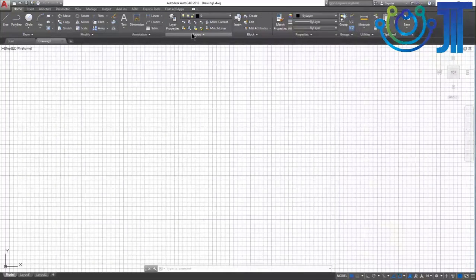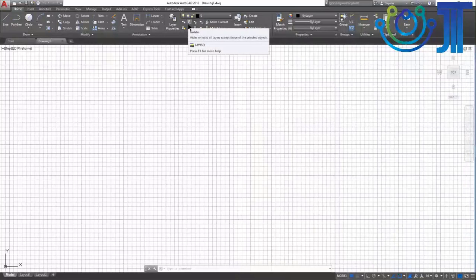The layers, as I discussed in the previous video, help you create one layer on top of another, so that when you want to remove or edit one particular part of the drawing, all you need to do is edit the layer in which that drawing is. You don't have to remodify the whole drawing. You can add layer after layer and edit that particular layer according to your convenience.